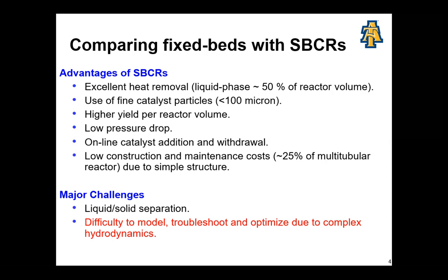As said earlier, the major challenges associated with this kind of reactor are, one, the problem of back mixing; the liquid-solid separation is quite challenging; and the difficulty in modeling and troubleshooting this kind of reactor due to its complex hydrodynamics. So we'll see how we're going to model this kind of reactor in the next slide.